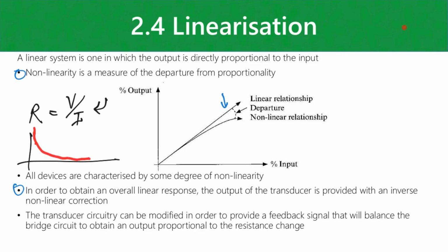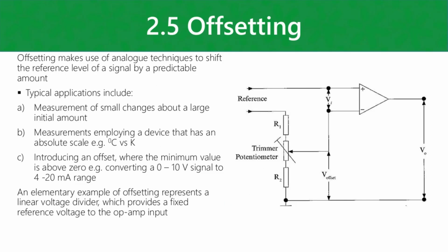But your resistance will be really, really low here, so as you can see, it's going to be a non-linear relationship. Now, in order to linearize that, you can use a Wheatstone bridge. That's actually why we use detector bridges and not just plain resistors to do voltage detection, because of this little problem. Okay, so I think I skipped ahead. Now we have offsetting.